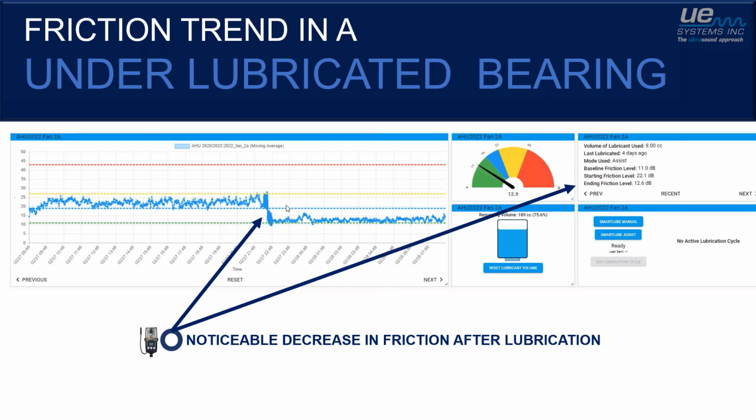So you can see here, in a matter of minutes between that grease hitting the bearing and that change in friction, the friction was able to drop dramatically, right? We were somewhere around 24, 23 decibels, and it brought it right down to what Mark was calling that sweet spot. And the important part too is it stayed there.